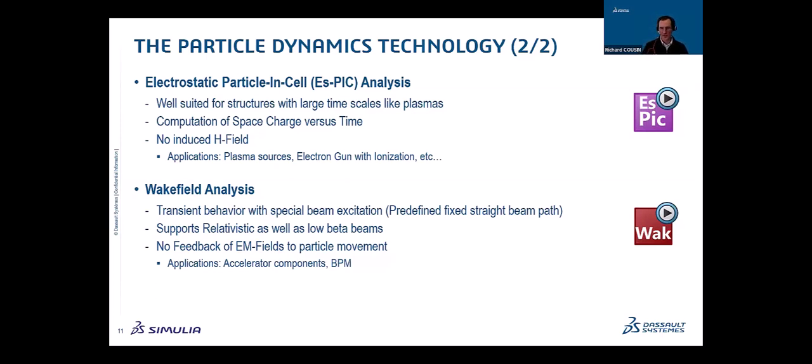The wake field analysis, the wake field solver, is a transient solver with special beam excitations. So the beam is really the excitation, so that means that the input is the beam, and you only compute the wake field, so that means the electromagnetic fields which are then induced into the RF structures when the beam is passing through the RF components. It supports relativistic as well as low beta beams, and that's well suited for accelerator components and beam position monitors. So all the diagnostics that you would have to take into account for an accelerator, for instance.